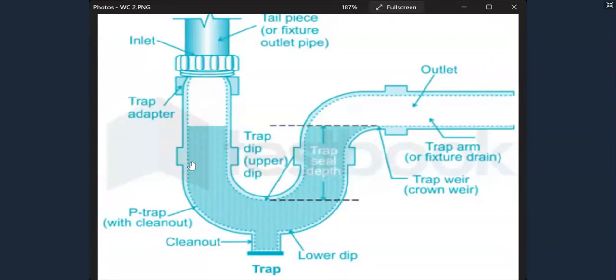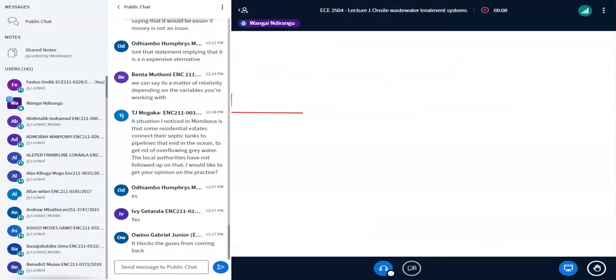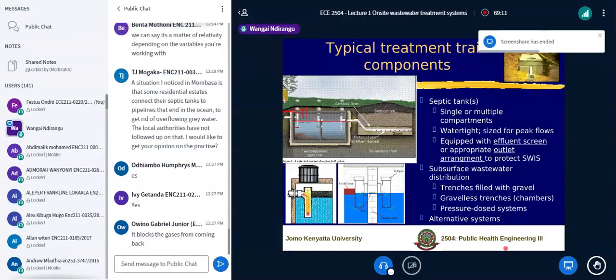So this water seal is very, very important in a water system. To avoid these gases from coming there, now I go back to my earlier slide. We ensure that this is buried inside the water so we at least minimize the gases. Of course, you also have the vent. When constructing a house, we provide a vent pipe so that instead of those gases accumulating next to the seal, they go into the air. It's simply a functional thing.